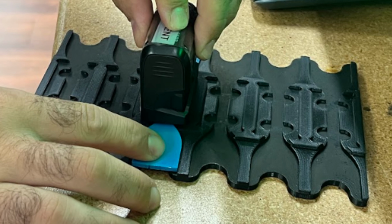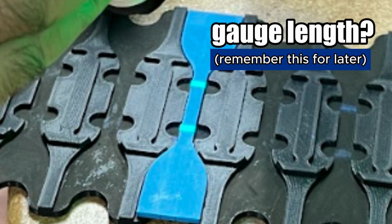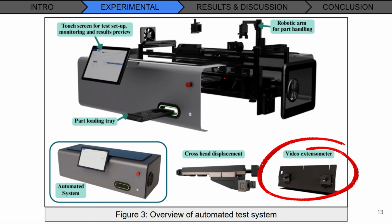So if you think about the Labs Cubed automated system, they use a fluorescent ink that gets stamped onto the gauge length of the sample. And so the video extensometer is able to look at those markings and track them throughout the test. And then a contact extensometer gets put directly onto the sample, clamped on, and it measures how much a part stretches by directly stretching with the sample.